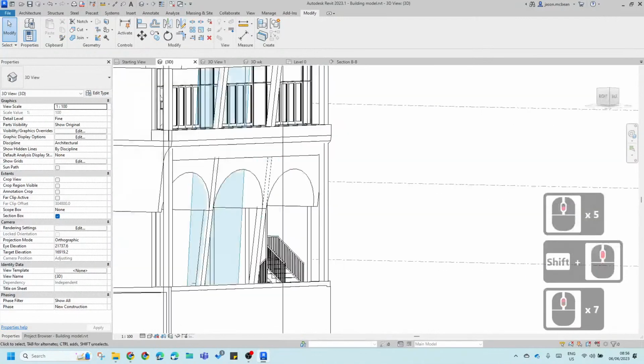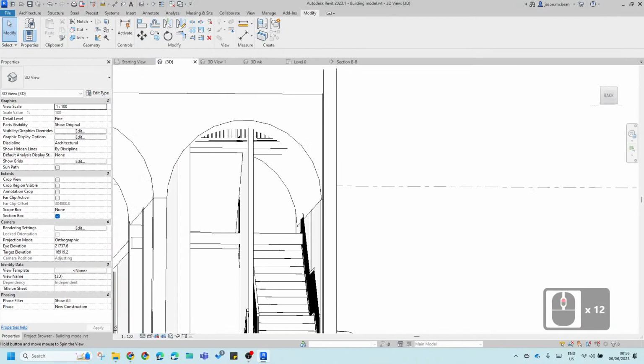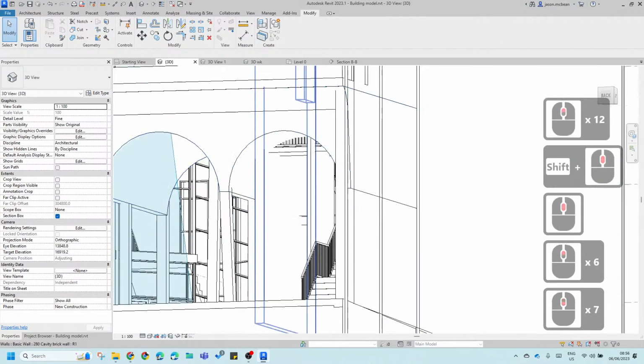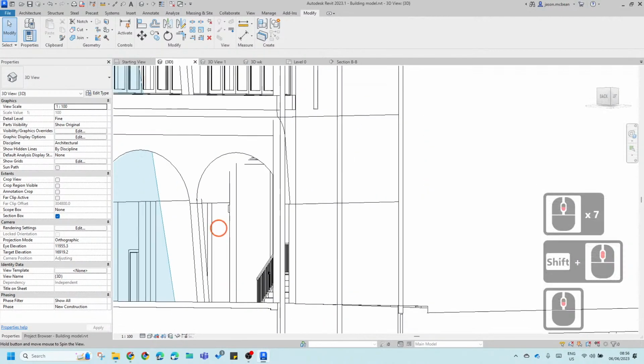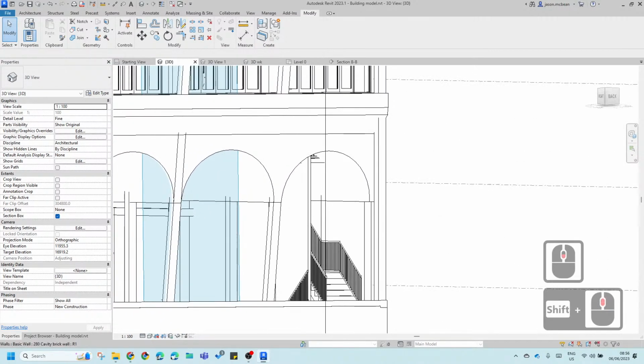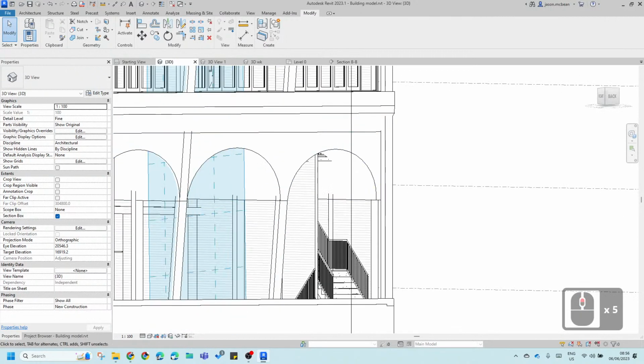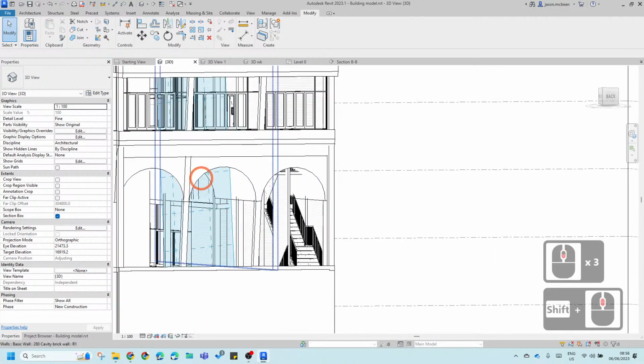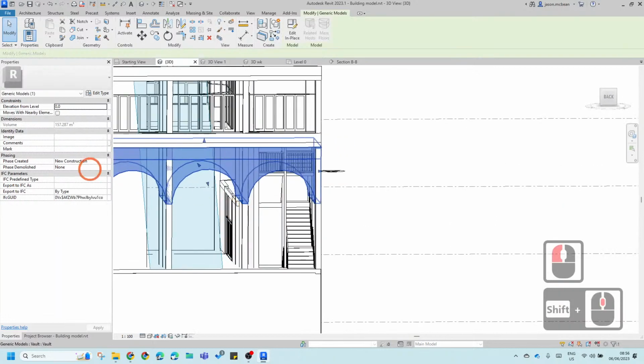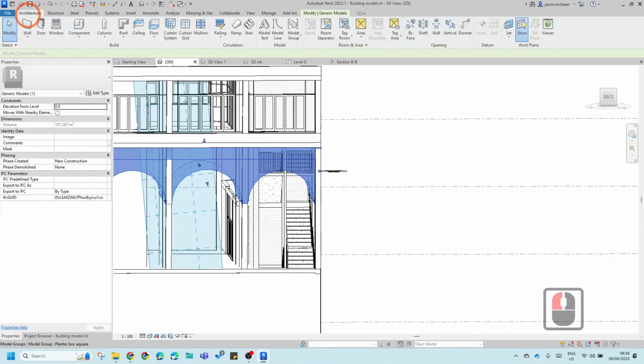So definitely doable. You can shape this any which way. Here you see it ties in perfectly with that column. There it's got a beam underneath. So maybe that's what you want to achieve, because here's another beam. This beam you'll actually break between there and there. It'll stop underneath there. But if you want to make this structural, what you can do is select this, and go to architecture.